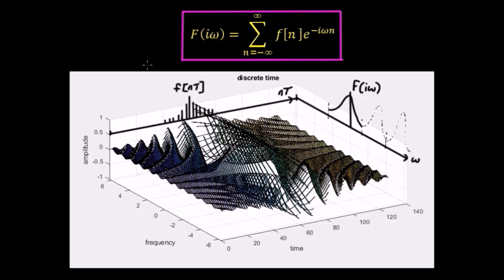Now another thing to note here is that we can rewrite the actual function and we can simplify it. So we simplify the nomenclature. So the discrete time Fourier transform, the f of nT, well, the value of T, if we normalise that to a value of 1, then we can just say that the number n will tell us the number of samples. So for example, we say here that T is normalised to 1, and we can just say that, say for example, there's 20 samples in that particular range of 1, which in effect would be 1 second.